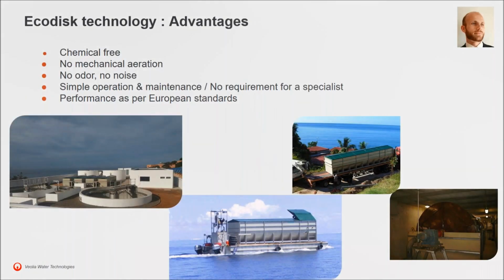So let's look a little bit more closely at the advantages of the EcoDisc technology. It is a chemical-free biological treatment, and because the energy for the aeration is provided by a single fixed-speed motor, its energy consumption is extremely low. Plus, the quality of the motor reducers and rotating parts that we use ensures a very low level of noise, below 60 decibels. The retention times are kept short, and as it is an aerated process, there are no odor issues. This is so true that most of our references in the Middle East are for units that are installed directly in the building basement.